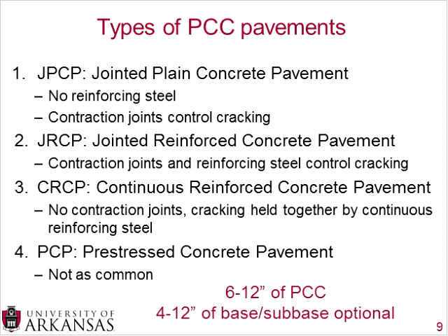A third type is continuously reinforced concrete pavement, or CRCP, which does not have contraction joints, and the cracking is held together by continuous reinforcing steel. So here you have the 3 options of steel or no steel, and contraction joints or non-contraction joints.